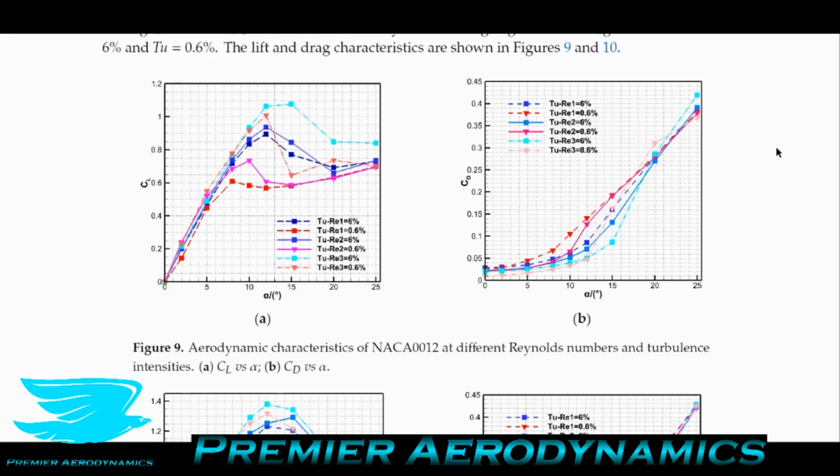So how does stall happen? When you have an airfoil, you have flow going over it. It will accelerate, and then it would see an adverse pressure gradient, the boundary layer. This adverse pressure gradient is working against this boundary layer to decelerate it. So then when the velocity in this boundary layer near the wall reaches 0 and even reverses, you then get separation.